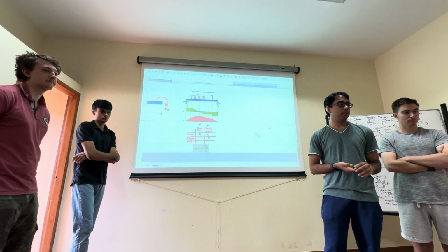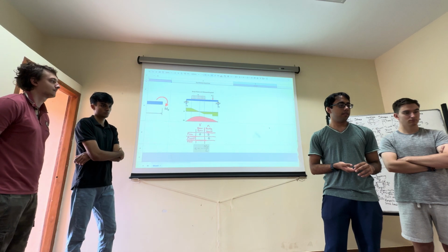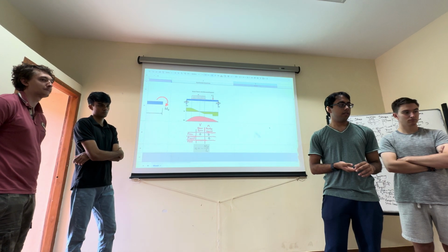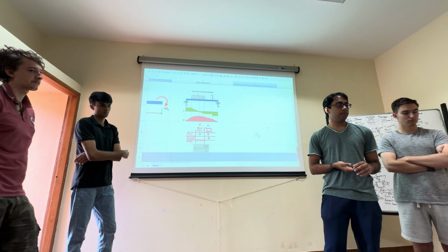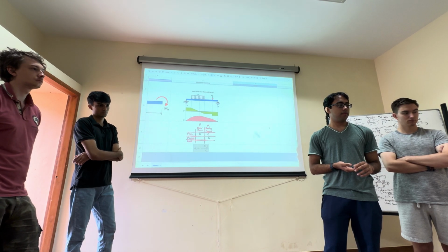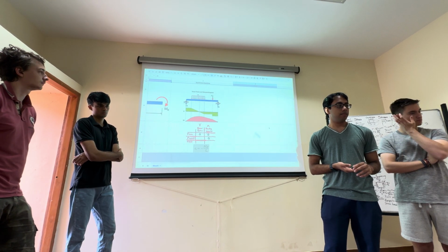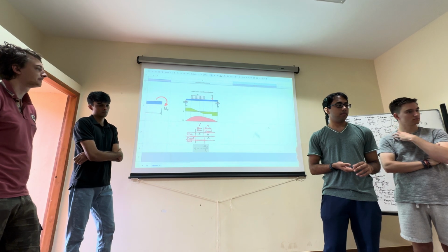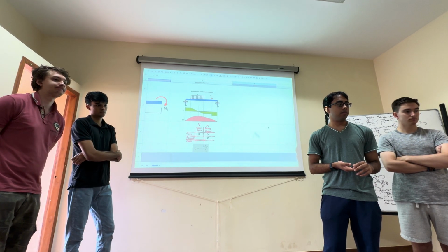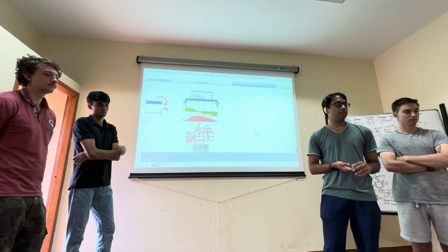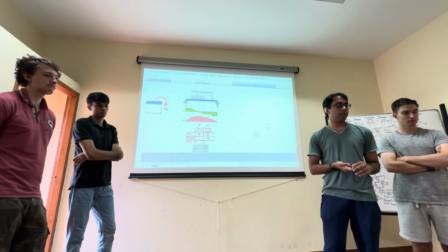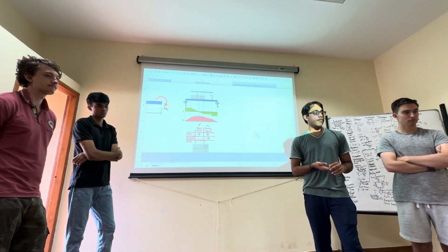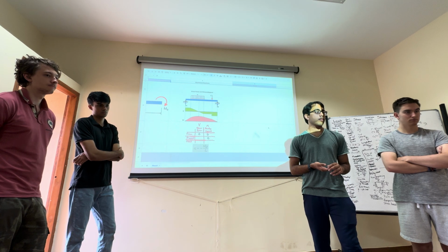So in your categories of equations, it's not only equilibrium equations, but equilibrium equations along with natural boundary conditions, which are essentially conditions about the load. Similarly, when you're talking about the kinematics, it's not only the strain displacement relationships. In dynamics, it will also be velocity displacement relationships, but also you'll have the geometric boundary conditions, like saying that if I'm fixing this particular end, then the displacement is 0, the rotation is 0.